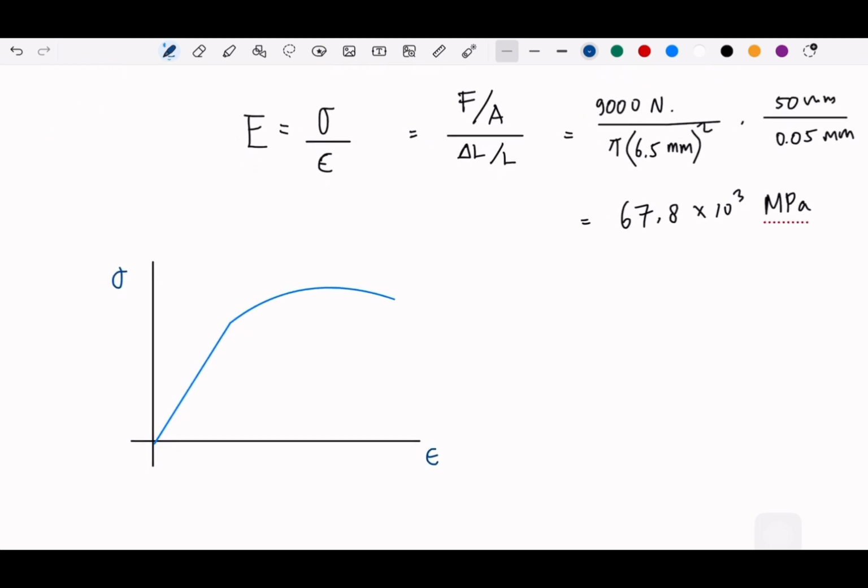And the proportional limit, if you take the offset 0.2, which means that we take 0.2 here, or 0.2%, so 0.002. And then we take a linear straight line like that, and we call this the approximation for the yield stress. Okay, approximation for the yield stress. So basically, here, let me write here.